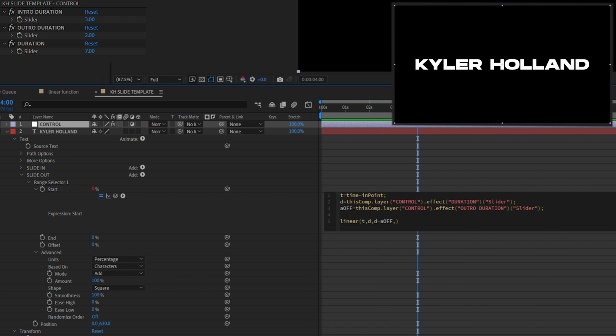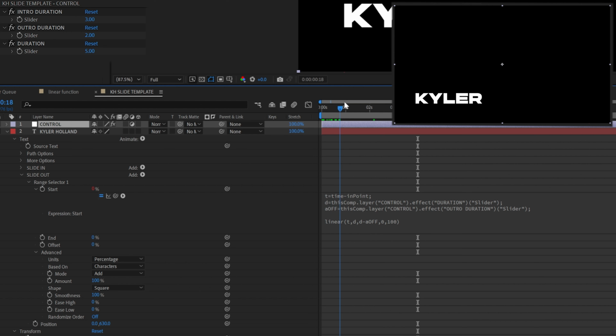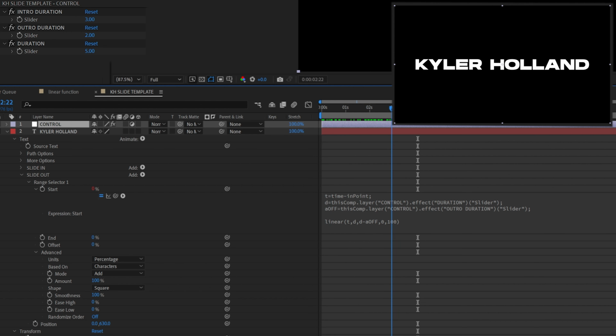And simply type a comma, and now we know that we want to go from 0% all the way up to 100%. So what this means now is if I change my outro duration to, let's say, 2 seconds, and then our duration of our comp to 5 seconds, you'll see that we animate in 3 seconds, and then right away, since our duration is only 5 seconds, our outro duration is going to start at 3 seconds, because we only have 2 seconds left.